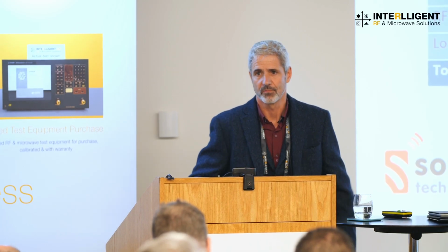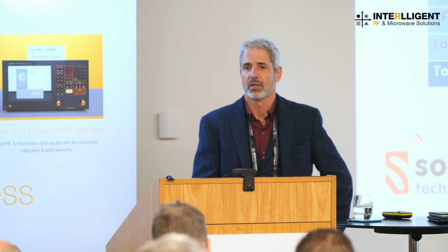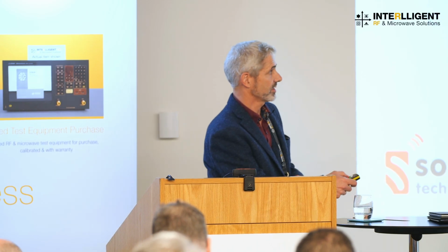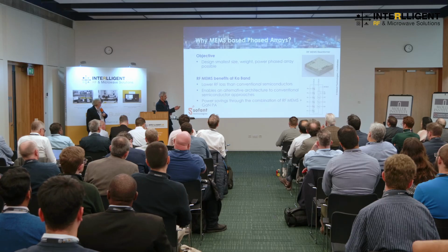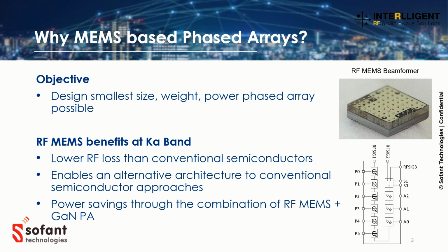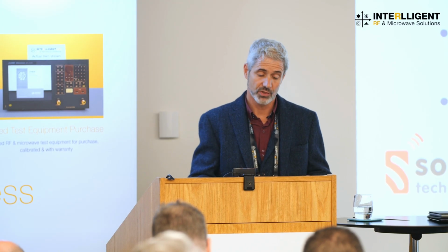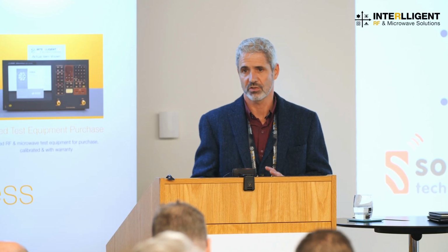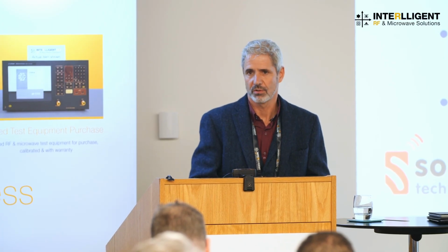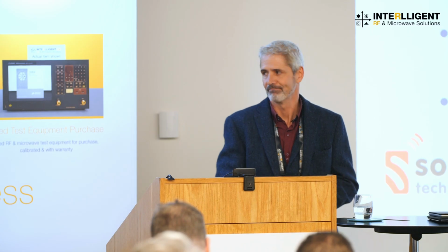In terms of the environment, do they operate in different environments? If you look back at the picture, this is classic MEMS. You can see it's a packaged device. This is a silicon die, and this is a glass cap. It's a low cost hermetically sealed package, because moisture can be a problem for MEMS. Other than that, we've measured them over temperature. There's no problem. The bridge is designed so it's consistent over -40 to +105, so it's robust.